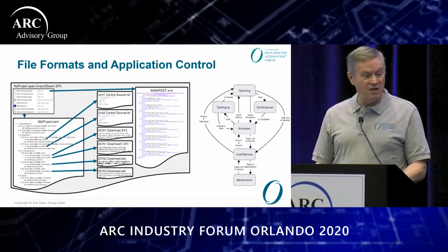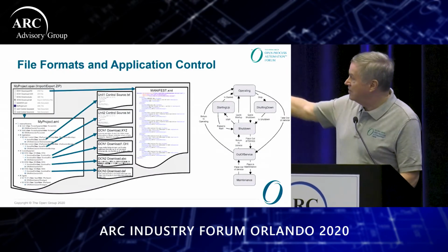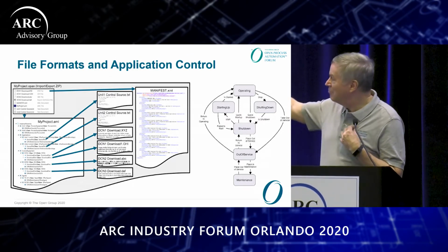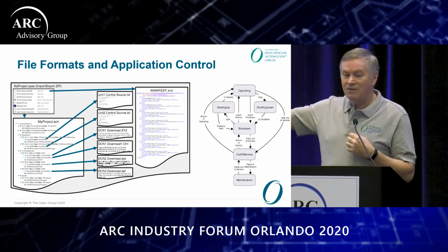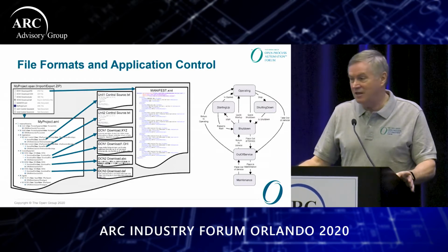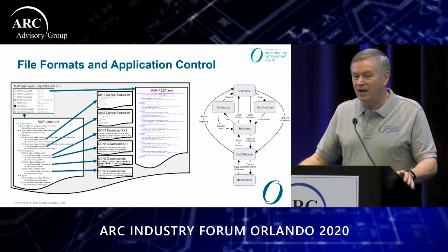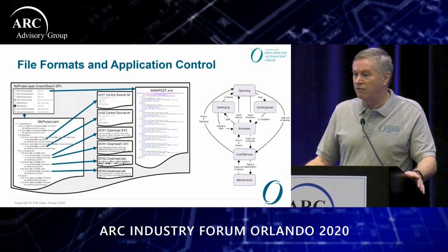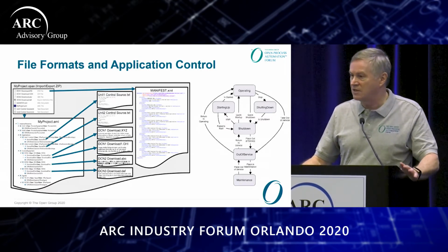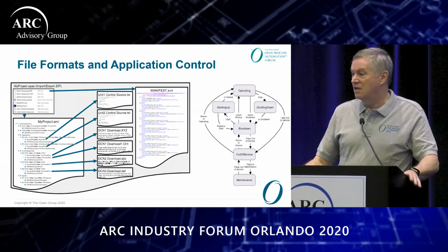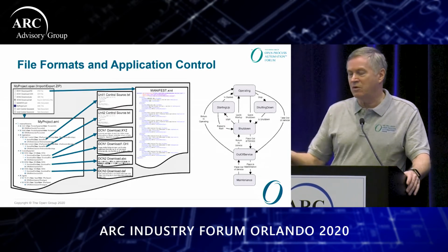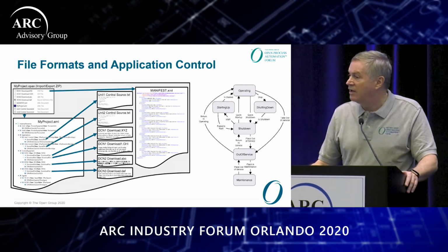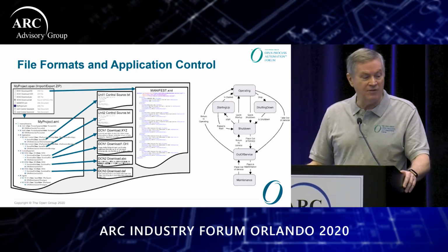So to give you some idea of what this looks like, and again, it's very difficult to read the small things. It's pretty much impossible to read these here, but you've got something which is essentially, as we said, a zip file. And within it, it contains an AutomationML file. That AutomationML file contains all the definitions of the tags, the DCNs, the execution engines, which are really the term that we're using for the layer I applications, and all the other information that's out there.